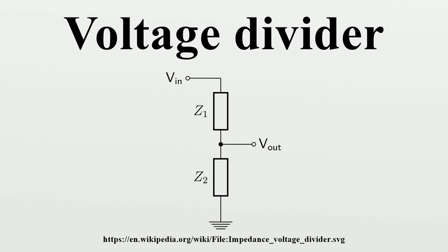Resistive voltage dividers are commonly used to create reference voltages, or to reduce the magnitude of a voltage so it can be measured, and may also be used as signal attenuators at low frequencies. For direct current and relatively low frequencies, a voltage divider may be sufficiently accurate if made only of resistors, where frequency response over a wide range is required. A voltage divider may have capacitive elements added to compensate load capacitance. In electric power transmission, a capacitive voltage divider is used for measurement of high voltage.